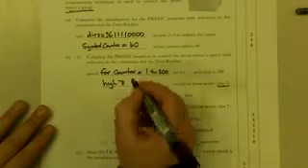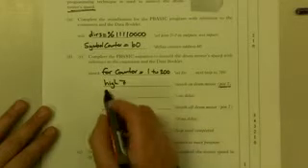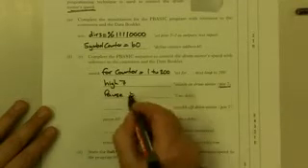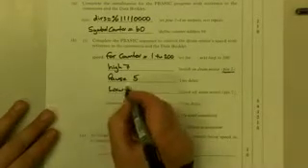It then says switch on drum motor, so it even tells us that drum motor is connected to pin 7. So a simple high 7 would do that. 5 millisecond delay, so it has to be a pause 5, and then switch off drum motor, low 7.